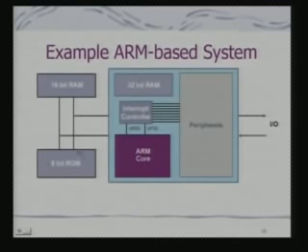So, external memory you can use of different kinds. These are 8-bit ROMs or 16-bit RAM, but they have to be organized such that they provide the 32-bit address reference. So, this is a very simple ARM based system. In fact, this is a generic architecture of all ARM based embedded applications, including many of your mobile phones. In fact, Nokia actually used ARM based SoCs in their implementations.